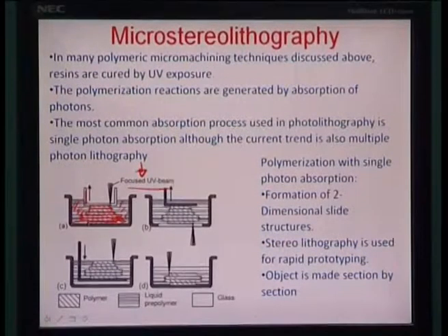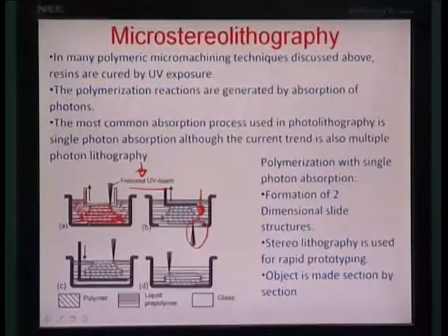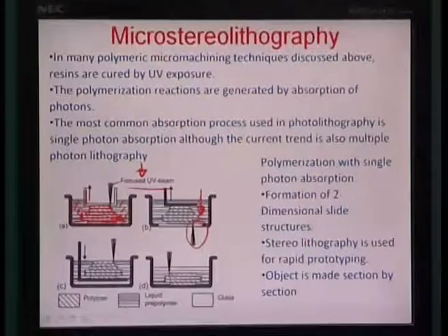Now, you can also use the same technique by putting the laser beam in the opposite direction and start writing more in a top down manner. So, you go selectively from top end to the bottom end, as you can see in this particular illustration. The idea is that you are writing whatever feature you want by sectioning into thin pieces and writing exactly along. So, the laser head which focuses the light is also CAD defined, the path is defined by the CAD package, the cross sectional area that you are defining onto the microstereolithography system by the CAD package.